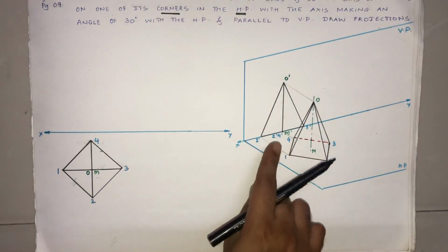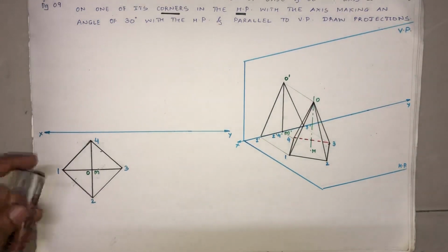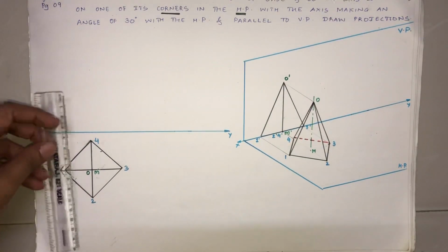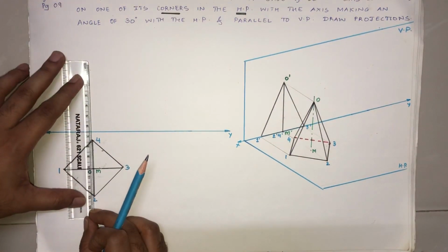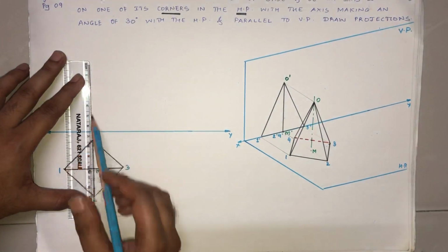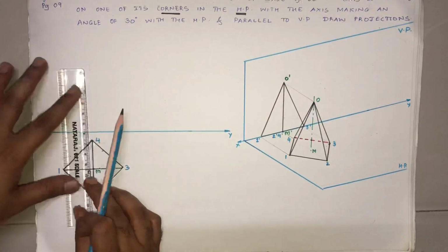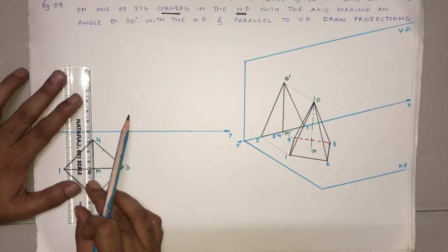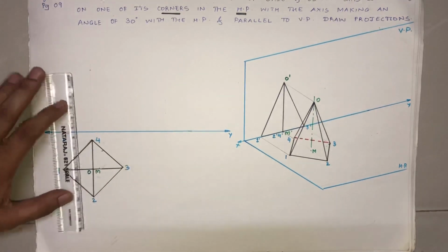We are going to draw the exact same front view here. Now what we are going to do is, in this way, we are going to project the axis point. OM was the axis point above, a light construction line, and I'm going to measure the axis height as 60. So here I'll just measure, name the point here, mark the point here like this.